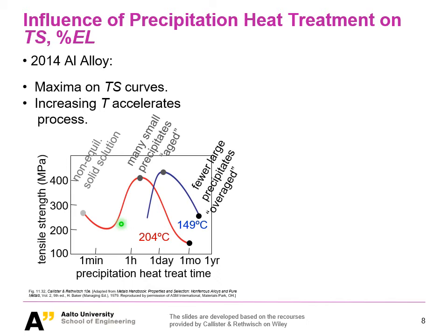In some cases it can even be soft. The main idea here is that they should be small. They should be small enough to create all these boundaries, and appropriate to induce some distortion of your crystals. Both of these, either boundaries or distortion of the crystals, give rise to the strength, because the dislocation mobility will be hindered by them.